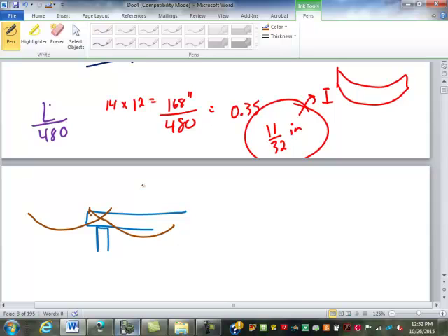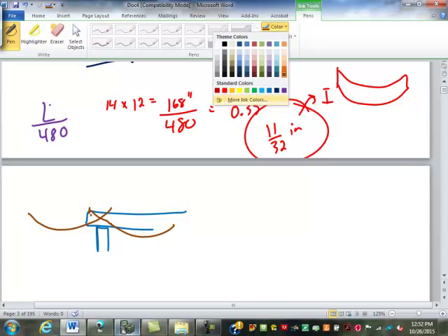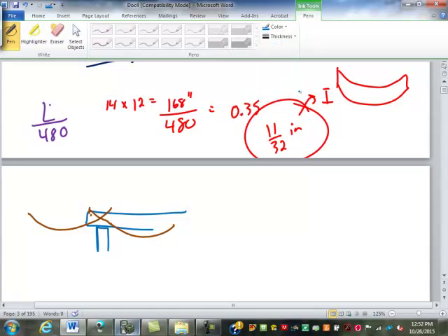I've seen people just take the I-joists, the TGIs, and just run them past and not cut them at all. So I've seen them overlap like 4 feet, and they always have squeaks in their floor. I've seen a couple where it actually busted through and cracked the flooring.